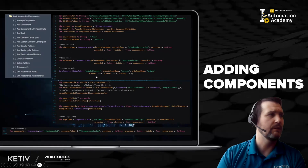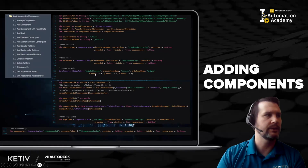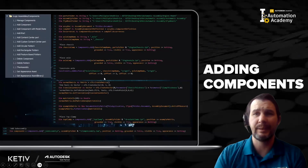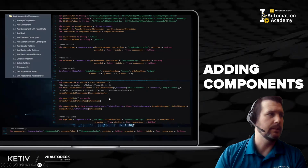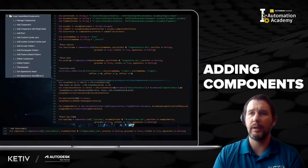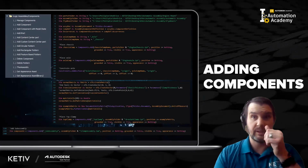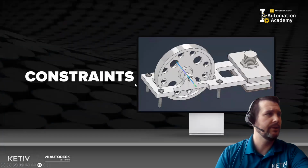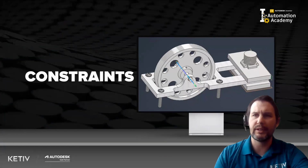We're going to look through different versions of how to add the components, whether we're looking at constraining them, or placing them specifically and then grounding them there. So that's what adding components is going to look like. After we're done looking at the full agenda, we'll jump into Inventor and look at it. After we add the components, we're going to be looking at constraining the components. We want them to be able to be tied to different parts and origin planes and different stuff like that.